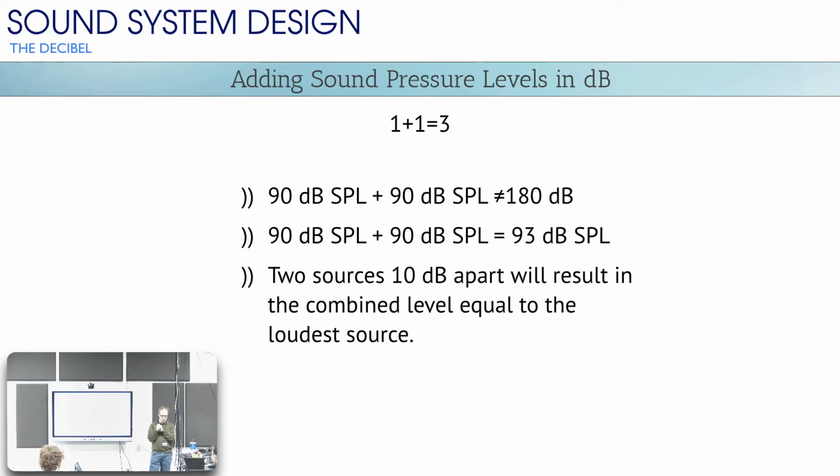are omnidirectional. No, I haven't taught you about directivity yet, so it can't be that. Say again? Close. So the wavelengths are larger, right? For a low frequency, it takes a much longer offset of distance to create a cancellation. So unless the two things are really far apart, it's unlikely that the really low frequencies are going to cancel out, because they haven't quite gotten to that 180-degree phase shift yet. But they only have to be offset by a few inches for high frequencies in order to create destructive interactions.